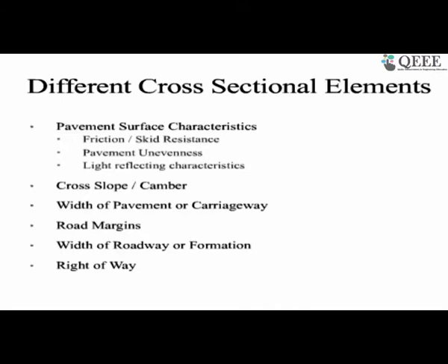And then apart from the roadway, on the pavement surface on which you are traveling, you will see there are certain other reserved land parcels on both sides, or empty land parcels, for various purposes. Somewhere there is a footpath, and there are signs, there are longitudinal drains. All this is included in the road margin, so the extra land width on both sides of the roadway is the road margin. I'll show you through a picture what this road margin is, where we need it, and what can be accommodated in that part.